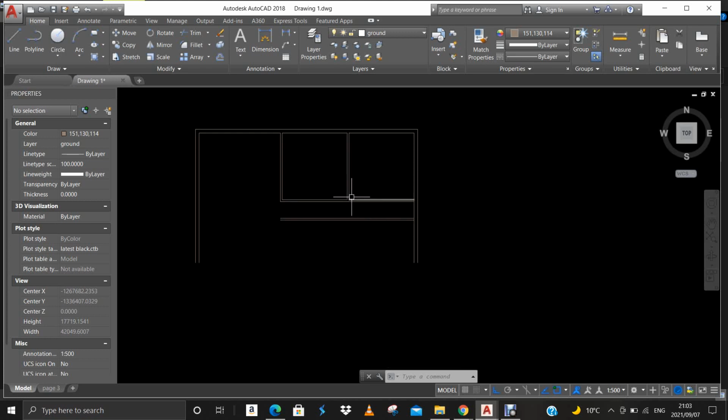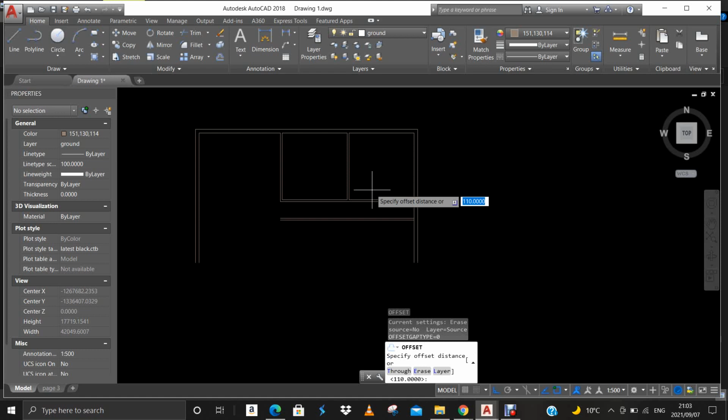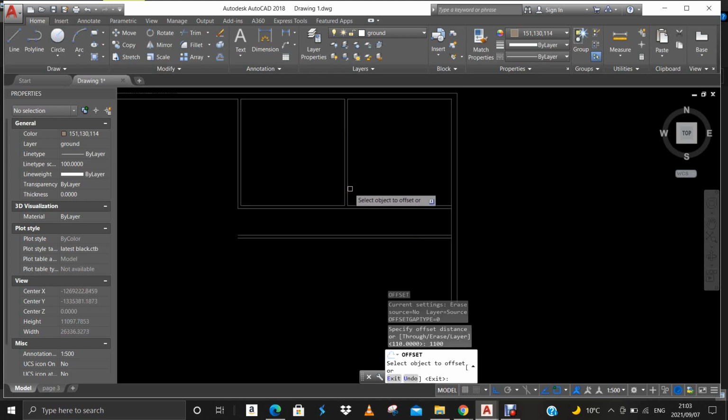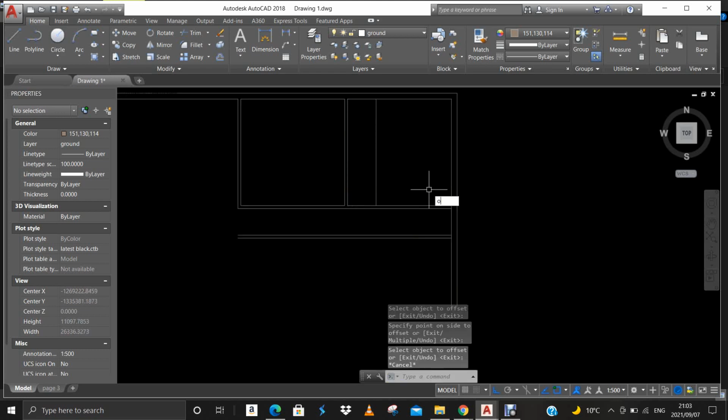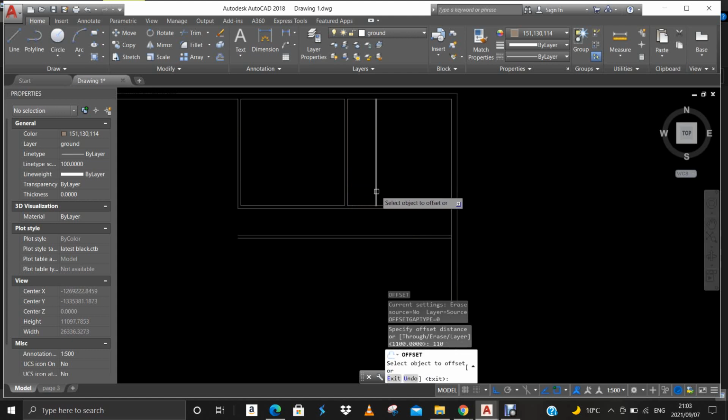and I want the entrance to this bedroom to be here and this one to be here. So here I'm gonna just check, maybe I must offset from here to here about 1 meter so that I can include the door. The offset, I'm gonna go 1 meter, let's say 1 meter 100. There you go. Now I'm gonna offset again and type an internal wall.